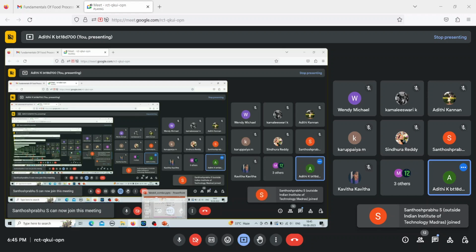So generally for highly viscous fluids, you will need an evaporator with an agitator, and unless and until mentioned, a jacketed open kettle evaporator is an example where an agitator is installed. So the answer is option C. Generally in a falling film evaporator, you do not have an agitator, you just make the fluid pass through by the action of gravity. Very rarely, unless and until mentioned, will you have an agitator attached to it.